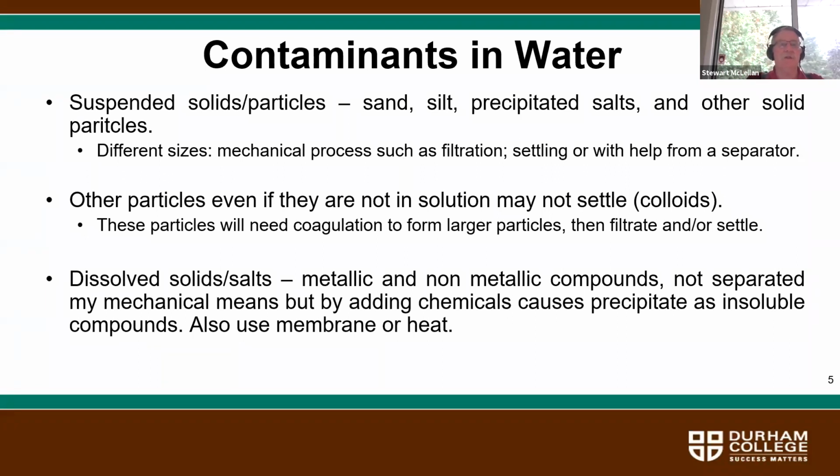Okay, when we get to the suspended solids and particles, typical suspended solids are sand, silt, precipitated salts, and other solid particles. These particles are there in different sizes, and mechanical processes such as filtration, settling, or separators are used to remove those solid contaminants from water. Other particles, even if they are not in solution, may not settle. An example that's given there is colloids. These particles will need coagulation to form large particles, then filtrate and/or settle.